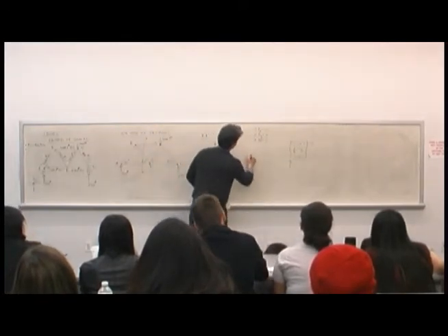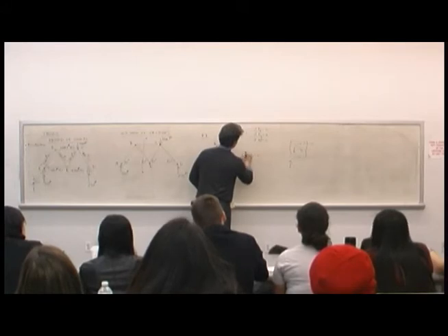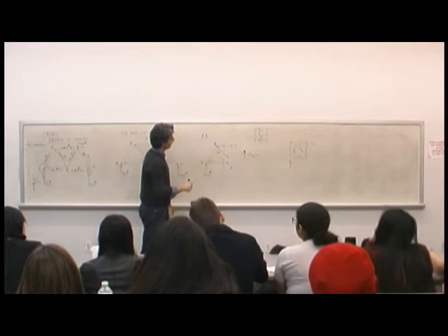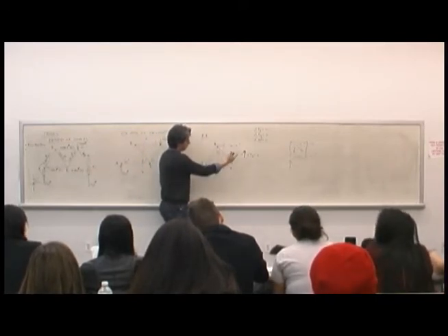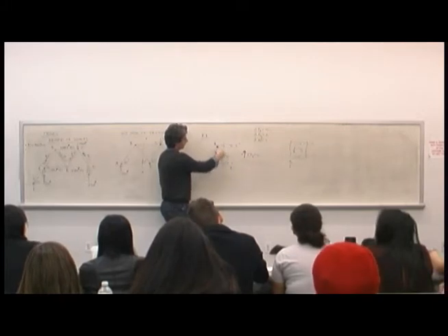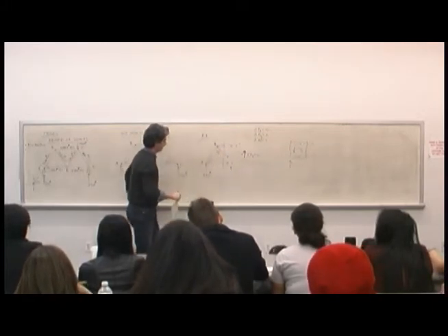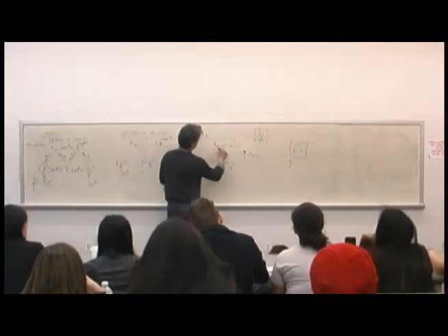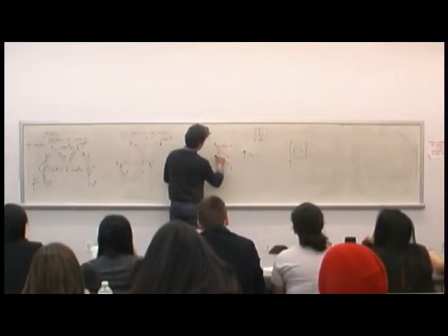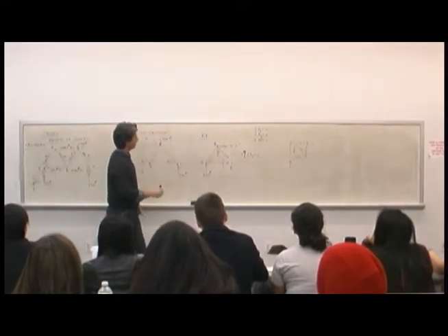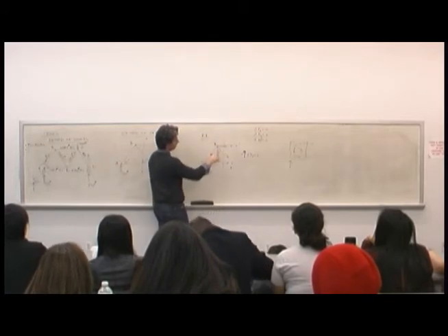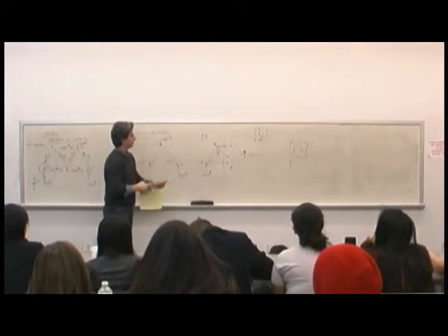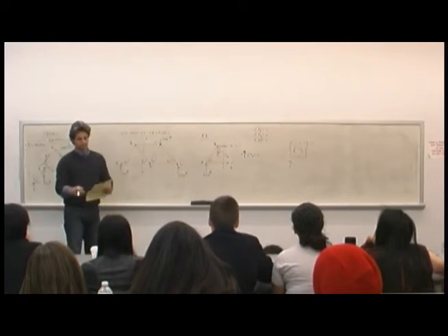I can look at the sum of the forces in the vertical direction, and I can imagine or look at this diagonal. It's the only vector I have that has two components, right? So if I take the components, I end up with something like that. Then I can add all my vectors in the y direction, all my vectors in the x direction. So what are the vectors in the y direction for this problem?